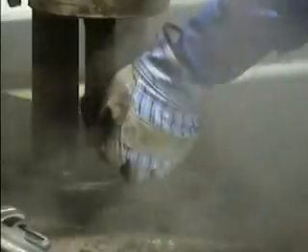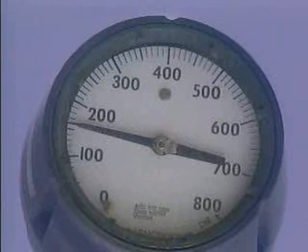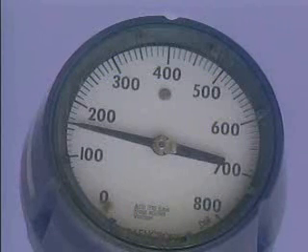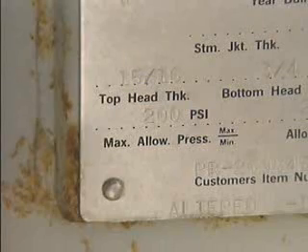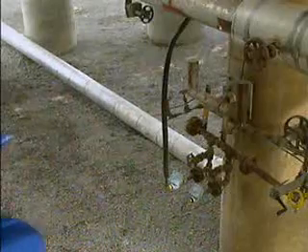You also need to know whether the system normally has a constant steam flow or a modulating or varying steam flow, because the type of flow affects steam pressure. It's important to check both the pressure and the temperature of the system's steam. First, note the steam pressure and temperature at the inlet for the equipment to which the system is supplying steam. Then compare these values with the recommended temperature and pressure for the equipment.